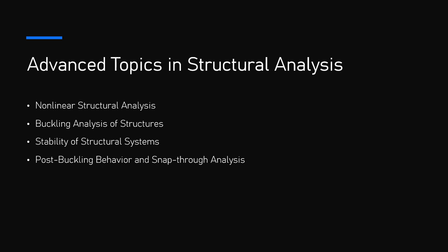10.2. Techniques for nonlinear structural analysis. Nonlinear structural analysis involves more complex numerical techniques compared to linear analysis. The key approaches include 1. Incremental iterative solution methods. Nonlinear problems are typically solved iteratively because the relationship between forces and displacements is not straightforward. The process generally involves solving the nonlinear system incrementally, applying a series of small load steps and updating the structural response at each iteration. Newton-Raphson method.